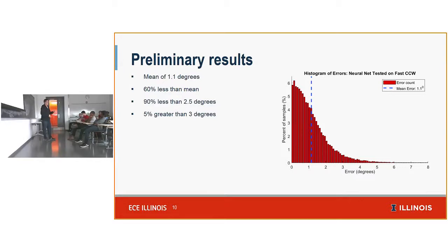The resolver has its own precision, and the resolver to digital converter board has its own precision. So both of these will limit how low we can go. And performance-wise, I think that is still dependent on the application. How much of the starting torque, for example, can you afford to lose, which will determine how accurate you need your angle to be.